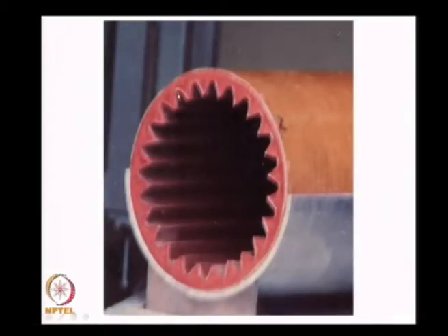See, this is how a pyrogen propellant grain looks. Well, it is just something like a solid propellant rocket, only you do not need so much of propellant. Therefore, I give a multi-point star. The red is what is the propellant. I have all these things. I ignite the surface, this generates hot gases, and that is what ignites my main motor.